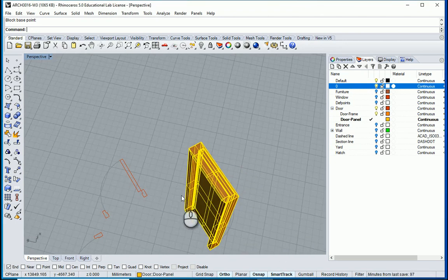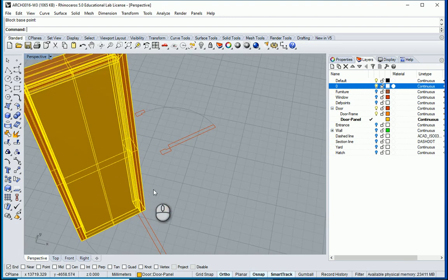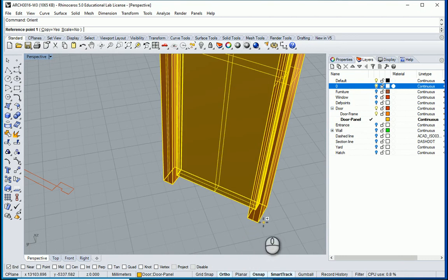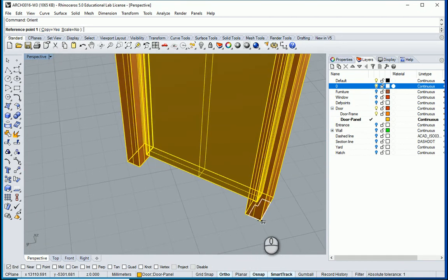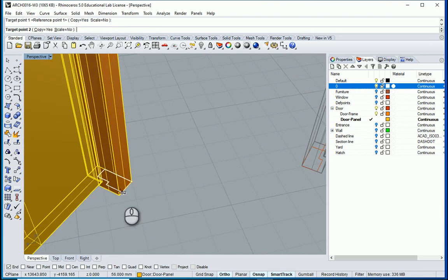Okay, now I can just copy or orient it over there. So I want to type OR. I know the height is the same. So from the copy should be set to yes. From this point to this point, it should go to this point to this point.